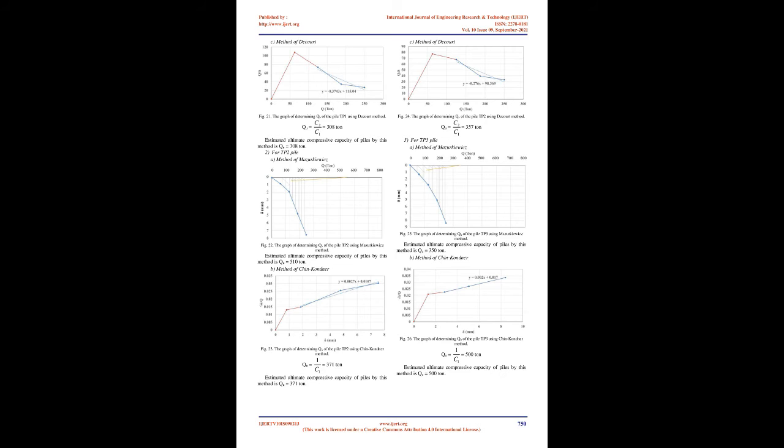Prediction of pile load capacity using the Vietnamese code. First, based on the geological cross-section in Figure 2 and the location of the pile, establish the actual geological column in which the experimental pile is placed. The stratigraphic column and the thickness of each soil layer in which the 4 piles in the survey are placed are shown in Figures 8 and 9. The pile diameter is taken as 600 mm and the lengths of experimental piles TP1, TP2, TP3, and TP4 are 37.9 m, 38.6 m, 41.8 m and 41.8 m, respectively.